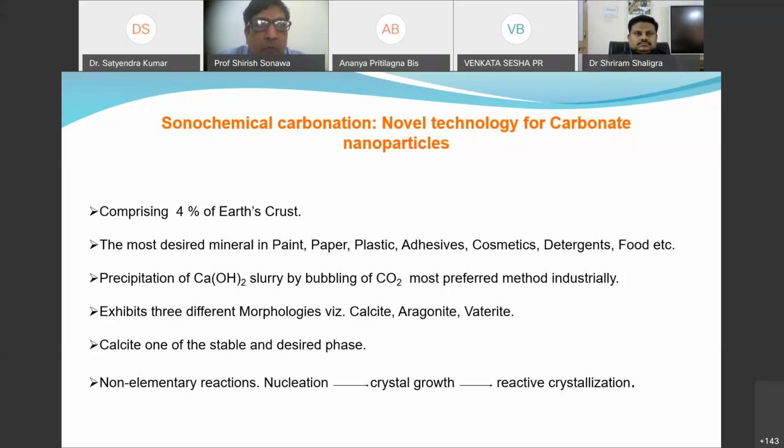So they take the stones or ore, burn it, and form calcium oxide. Then after forming calcium oxide, they hydrolyze it to make calcium hydroxide. Whatever CO2 has been liberated during this calcium oxide formation, they recycle and reuse that CO2 gas, put it into the calcium hydroxide to make the final calcium carbonate. This is used in a batch process for calcium carbonate production. But the reaction takes around 2 hours, and again there is the issue of particle size distribution.